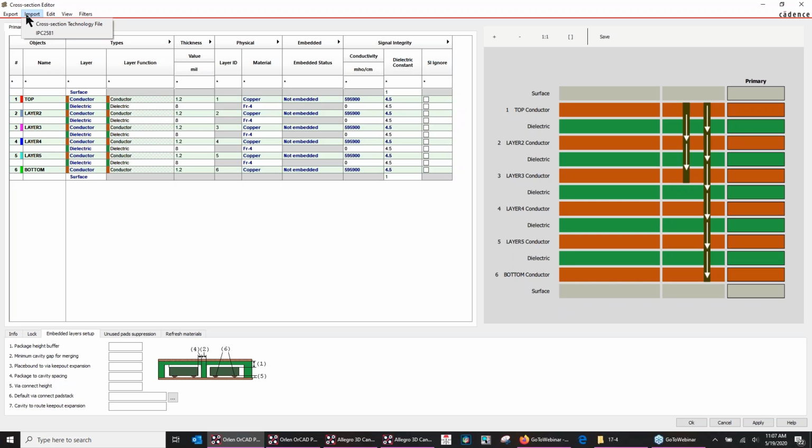The thickness, copper thickness, dielectric material, that's all very important information. Our software uses that. Even though you might have Standard, you could use it for other things in here, for signal integrity and other uses. Let's say you're outsourcing, or you're getting that through the EDA card, and then you're wanting it to check the ohms. So you want 100 ohms on your clocks for your memory, and you want 80 ohms for USB. This information is already in the database, even though you got Standard. You can move forward with Pro if you needed, and that information would already be there for you.